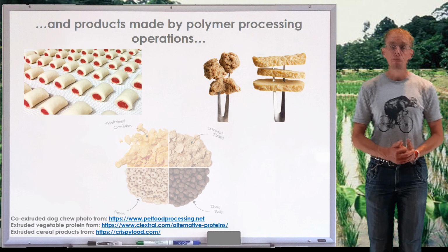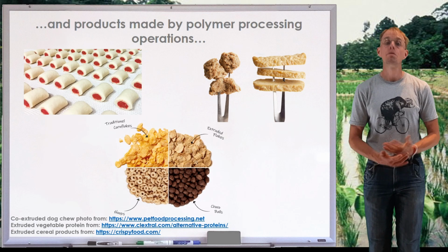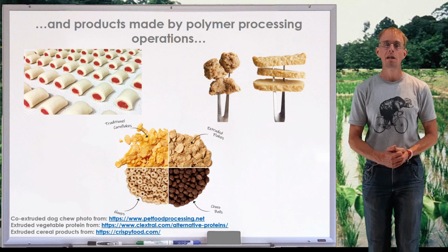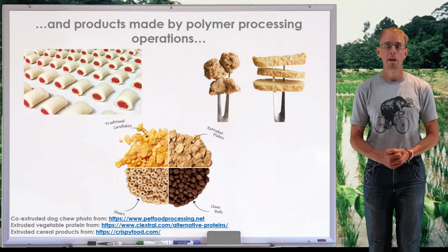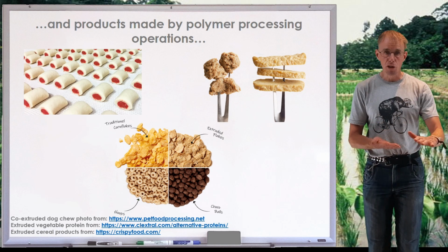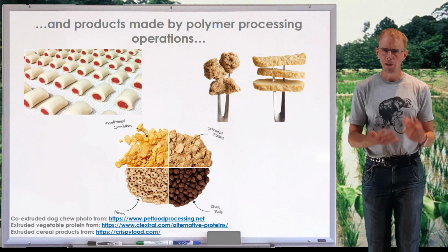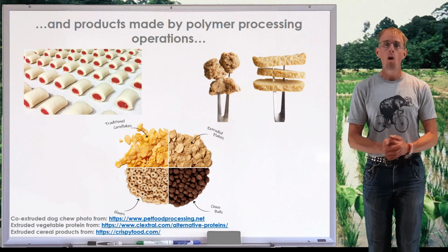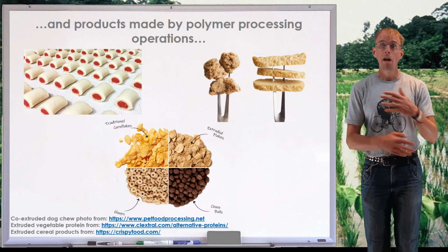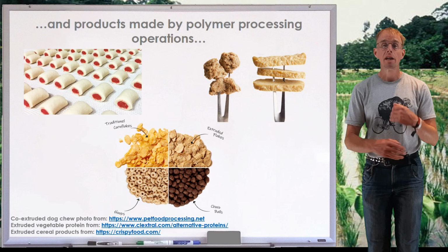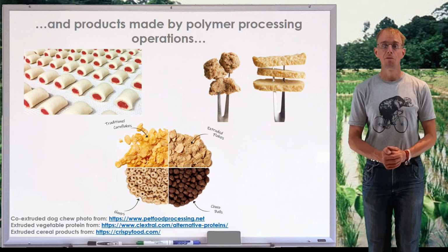First thing in the morning, you're probably eating extruded products in terms of breakfast cereals. So if you look at the range of breakfast cereals that are on the market today, most of them will be produced by an extrusion operation. So for example, traditional cornflakes might be produced by corn on, not quite corn on a hot plate, but that's popcorn, but there will be a production process that involves a cooking type method. Or you could use extrusion cooking, shape forming in the die, and then chopping, and then either drying or baking as appropriate to form the final product.